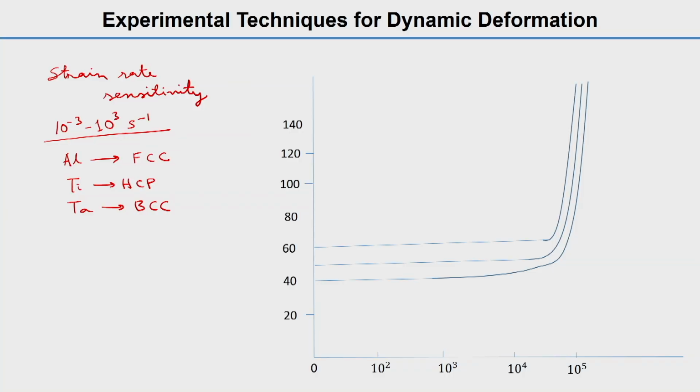We need to get the material parameters out from the experiments, let's say from the split Hopkinson pressure bar, and you now understood that those material parameters cannot be calculated from first principles. This curve that we want to show you in this slide is from a reference, Clifton's group, from 1983.